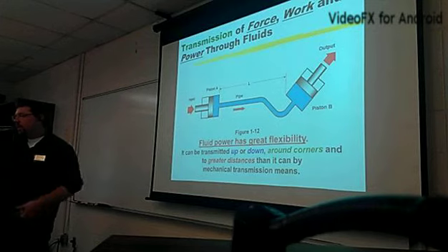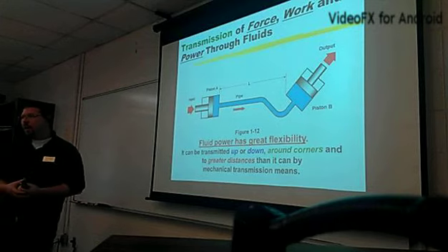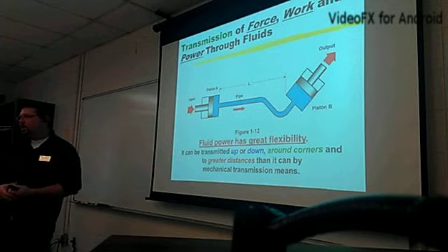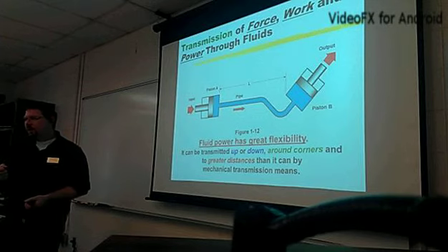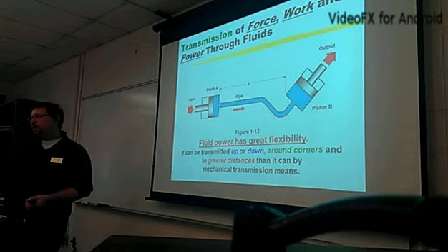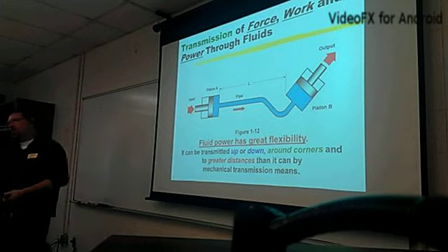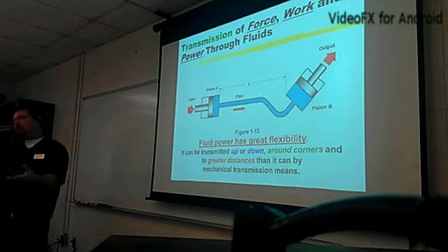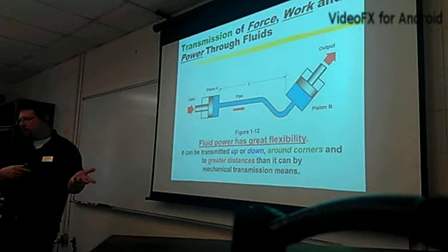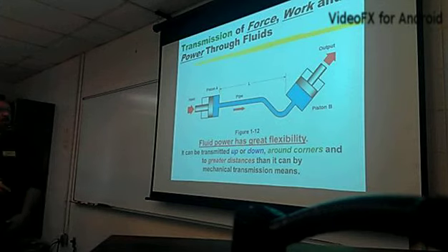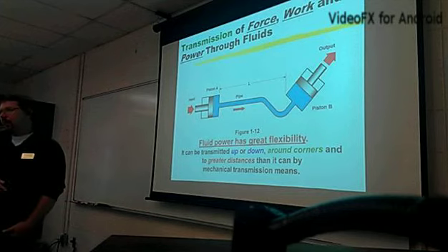It's much easier to manufacture a hollow tube with a plunger in it than it is to manufacture a big old cam gear system with a swivel anklet with a U-joint on it that would actually have a screw, so there'd be a gear and cam, and then this would go in and out. You can get them, but they cost more than a hydraulic system. All right. Also have a lot more that wears out on them. There's a lot more to go wrong.